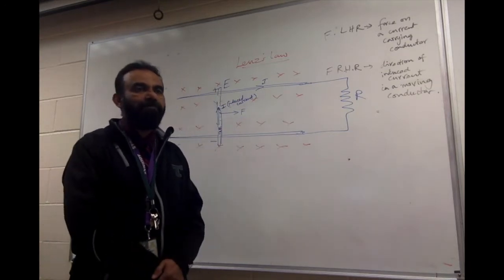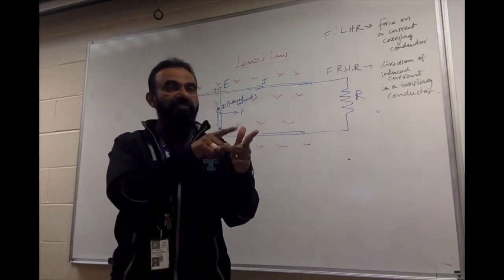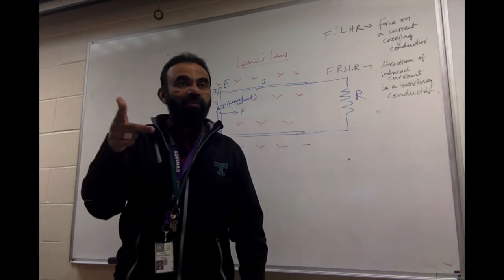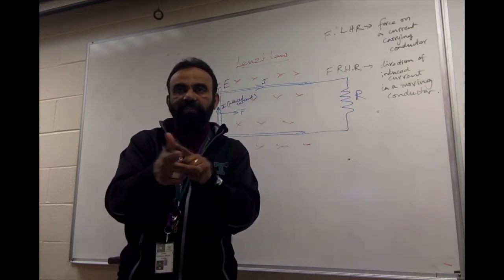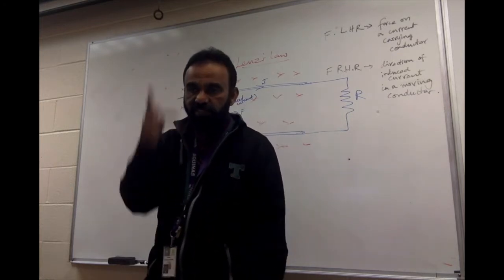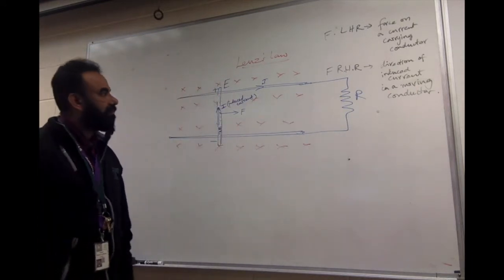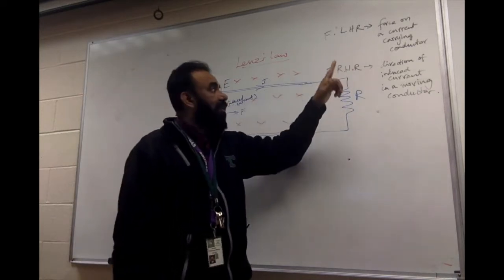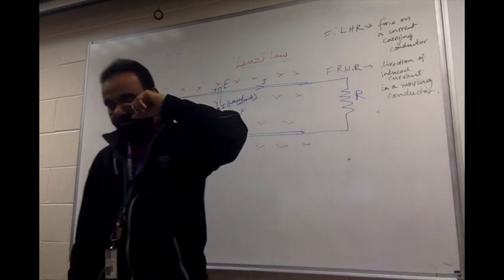What are the different fingers again? The same things, FBI, FBI. It's the same thing. But in the left-hand rule, F is something that comes as a consequence, because you're sending the current in a magnetic field. In the right-hand rule, F is not a consequence. F is what you are pushing. This current is a consequence, which is called the induced current. So if you're looking for induced current directions, right-hand rule. Whenever you want to find the force on a current-carrying conductor, use Fleming's left-hand rule. Whenever you want to find the direction of induced current, use Fleming's right-hand rule.